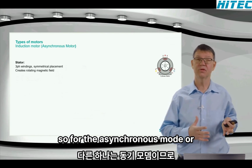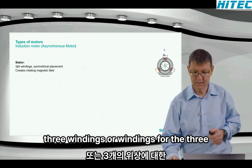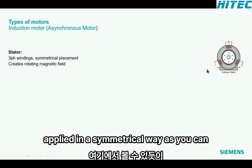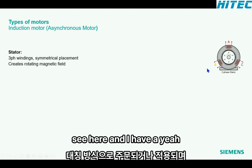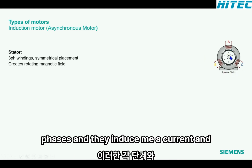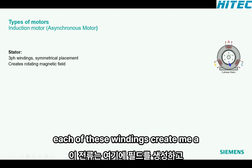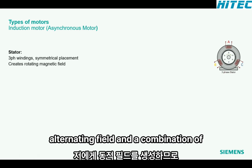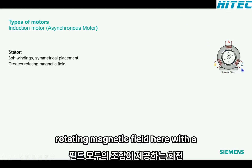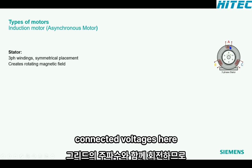For the asynchronous motor or induction motor, we have a stator, what you see here on the right-hand side, with 3 windings for the 3 phases, and they are applied in a symmetrical way, as you can see here. I have a sine curve voltage on each of these phases, and they induce a current, and this current creates a field. Each of these windings creates a dynamic field, so a sine curve, an alternating field, and the combination of all three fields gives me a rotating magnetic field with a constant amplitude, but this is rotating with the frequency of the grid, so the connected voltages here.